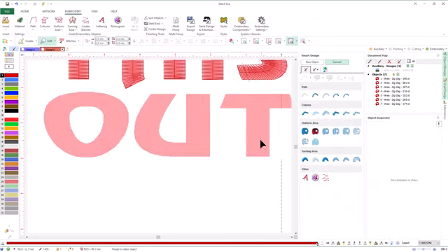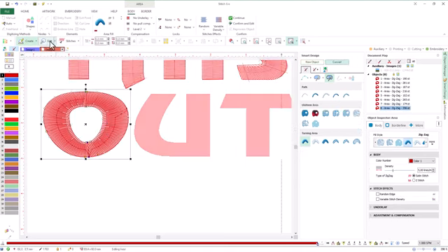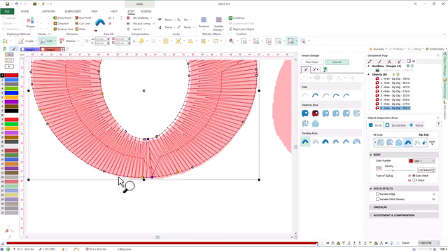Select turning area with zigzag and Auto-Complete. Click to capture. As we can see, unlike Auto Trace, Auto-Complete captures all the contours of the region, and not just one of them. Select Accept in the context menu, and check the object. Auto-Complete added a cut line and direction lines, as expected. However, it added direction lines at each side of the cut line to get a result similar to the cut line and direction combination we used before.